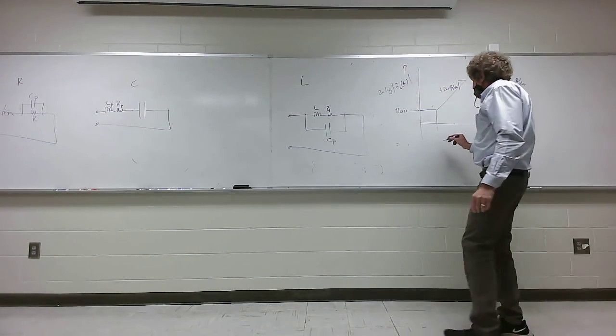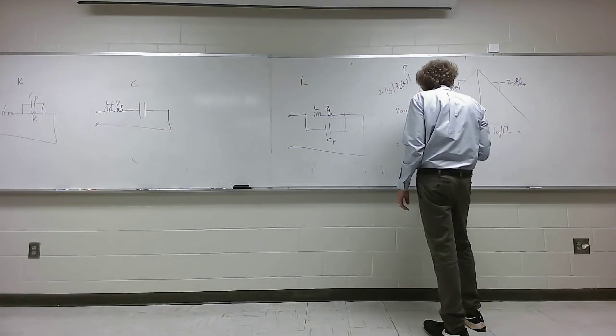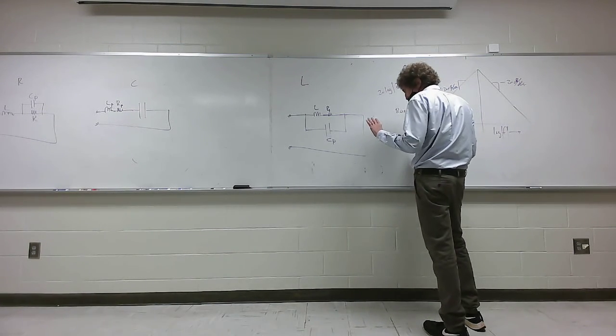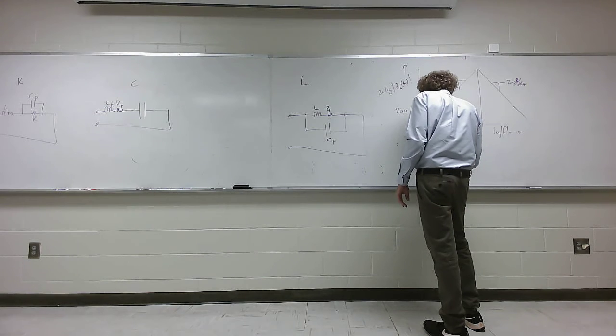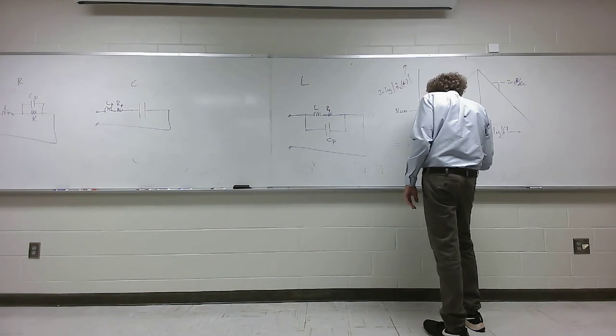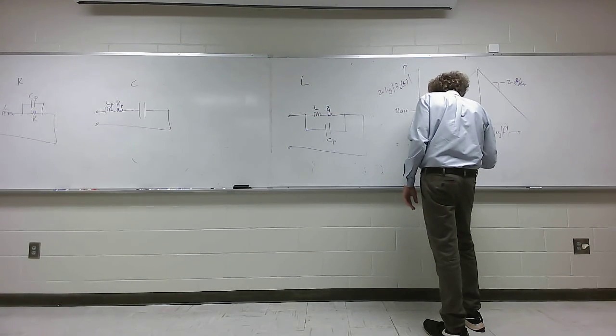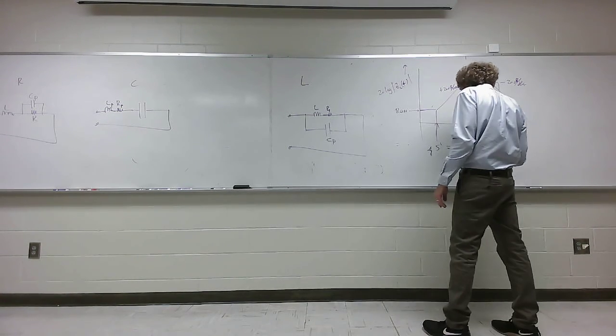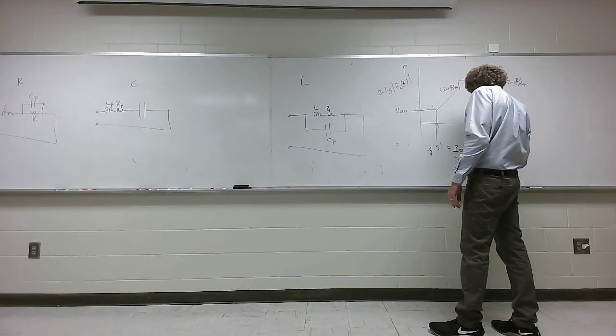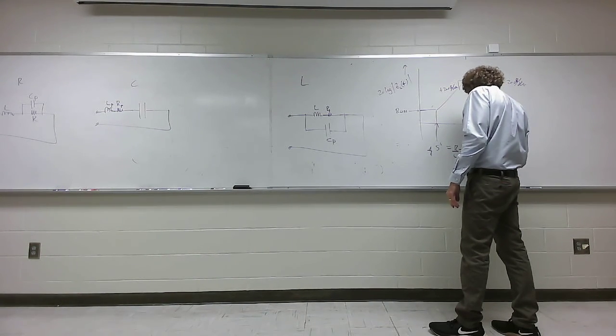Now, down here, this low frequency, and he doesn't talk about that, and this is not quite exact, when you put sL equal to R, where s is really 2 pi times F, you get this.